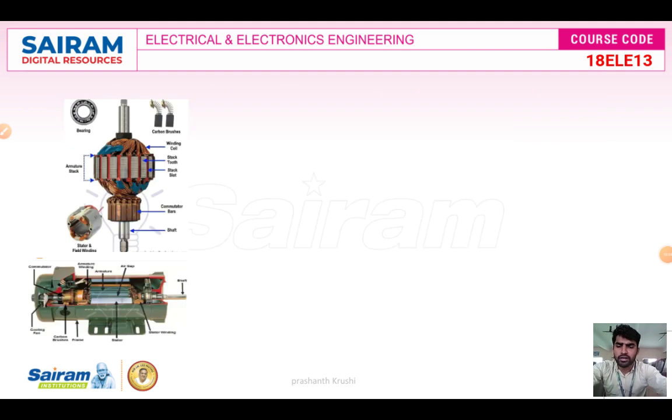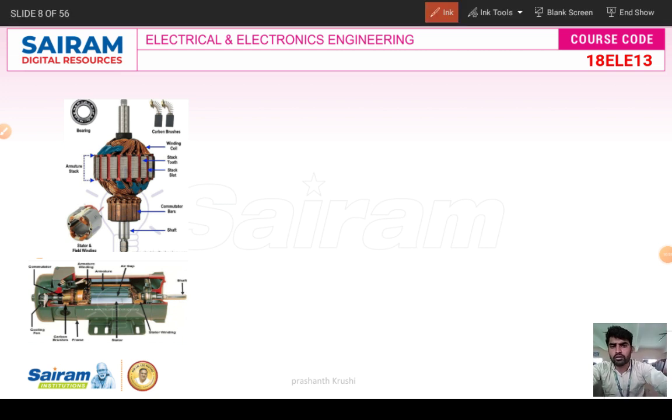These are the constructional parts, like stator and rotor. The rotor is this one. See here: commutator, slots, armature conductor, brushes, and bearings. Bearings are for smooth operation. The spring is for pressing the brush contact onto the commutator. This is the stator. This is the overall construction of the DC machine. The commutator is for collecting the current from the armature conductor, and also converts AC to DC. The shaft is for holding purpose.